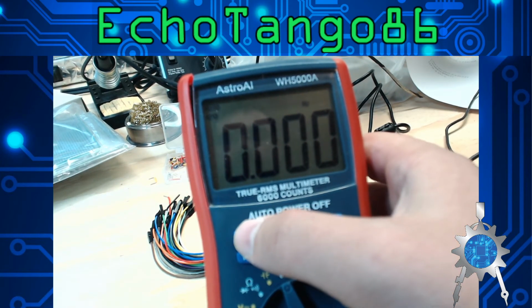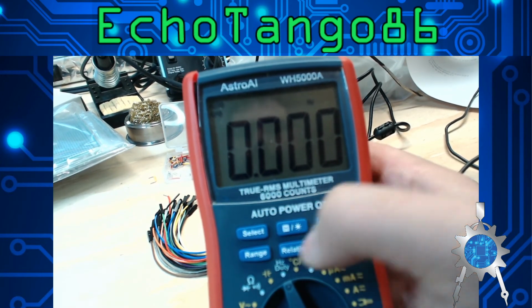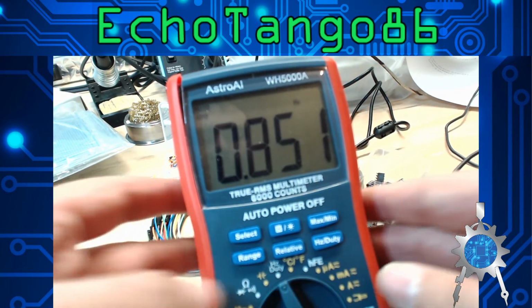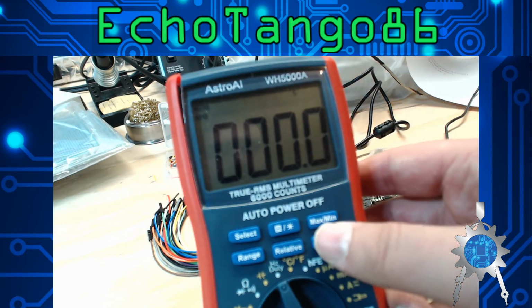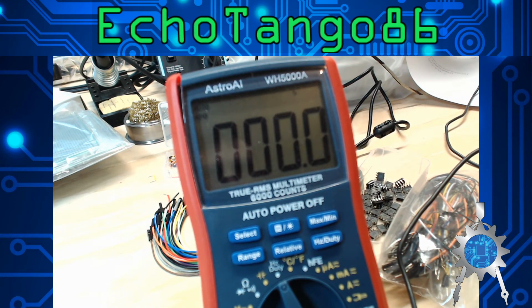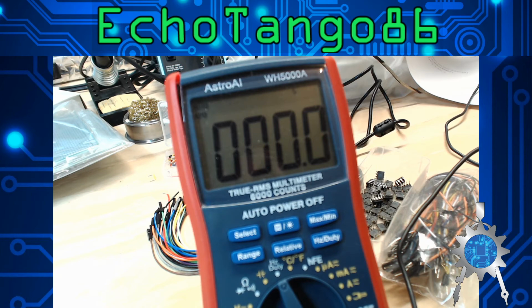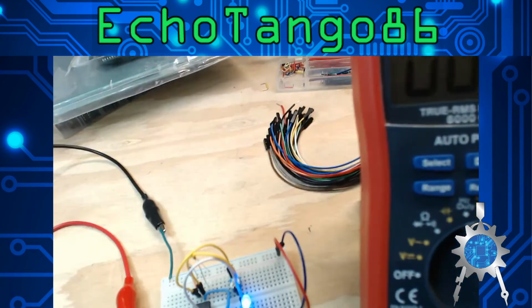I think if I select it, I can change it. Maybe it'll give me a period. Maybe not. Oh, here's the duty cycle. Is it 50-50? Hey, look at that. Almost 50% duty cycle, 49.2. Wasn't that what we were looking at in our math when we were calculating the two? So obviously that means that our potentiometer must be very close to that 860K resistance, which is pretty nice.